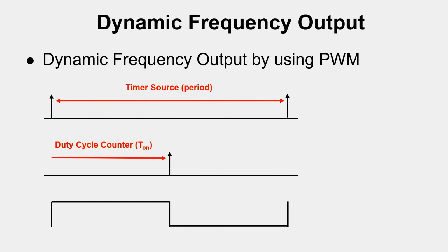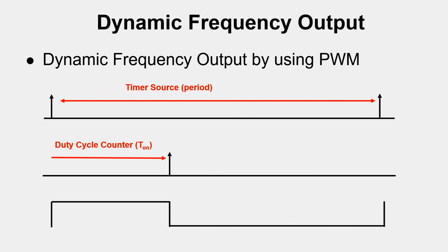Then you have to change two things in your PWM now. First, you change your timer source to longer, and then you change your duty cycle source. These are the two parameters, and you need to keep calculating on either the prescaler, your timer source, all kinds of elements regarding producing this kind of signal.